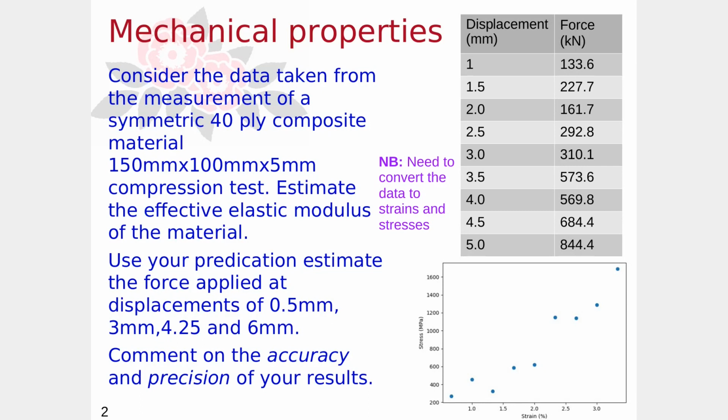So one way in which to do this would be to employ the methods of interpolation and extrapolation that we did before, especially since we've got a force. That said, the underlying physics can be applied here, and the underlying physics is probably linear elasticity, looking at the amount of strain is up to about 3%.